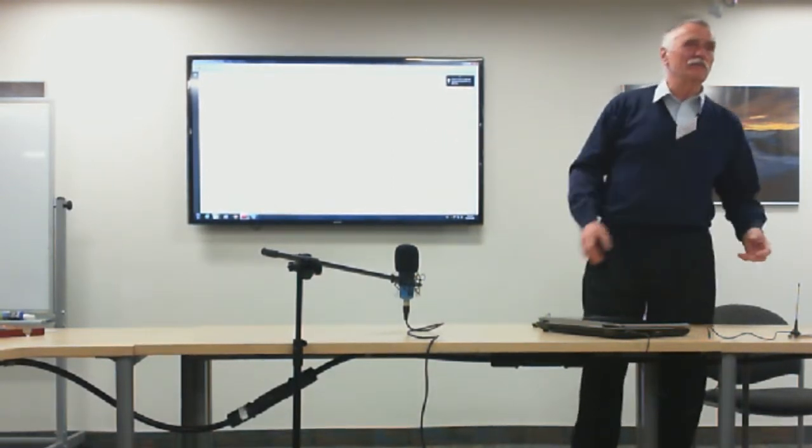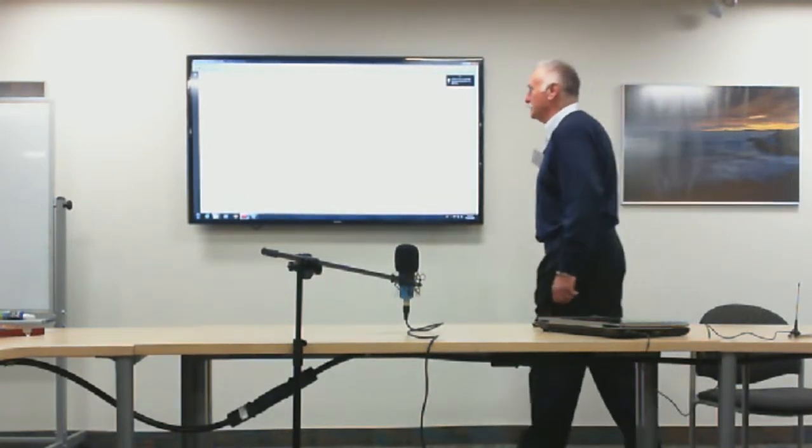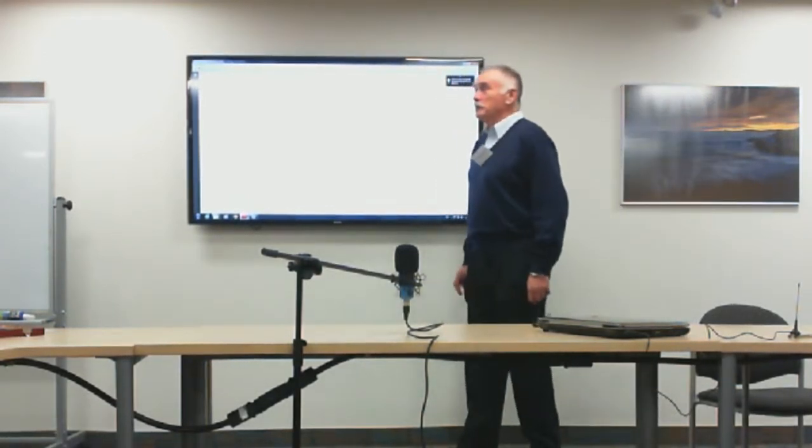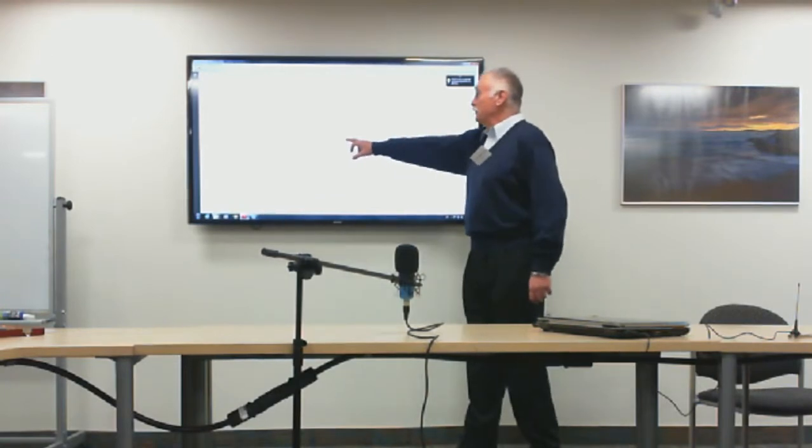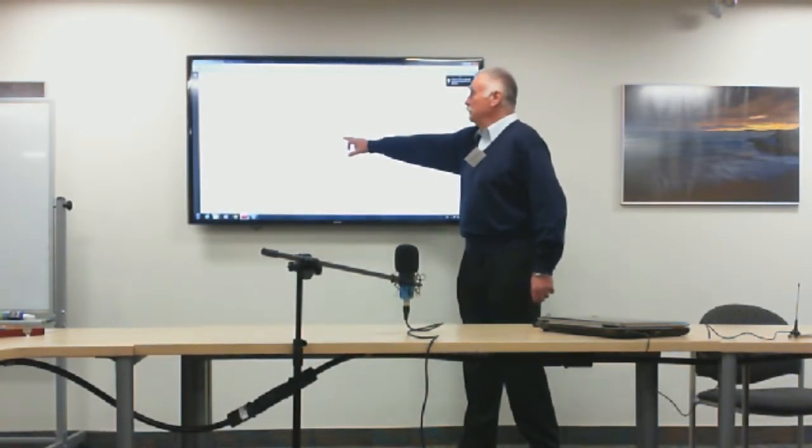While you are receiving, impedance match is a great feature, but you already have it implemented to be able to transmit. So when your receiver is also impedance matched, there is a receive advantage as well, because the receiver also benefits from maximum power transfer between the antenna and the receiver. Power that goes into the radio is voltage squared over R. So the power is extremely small.